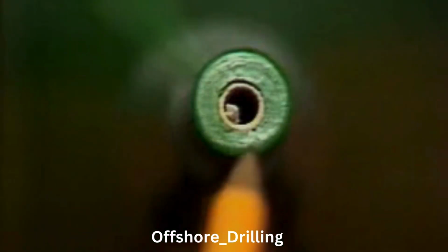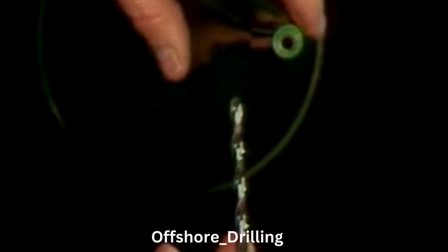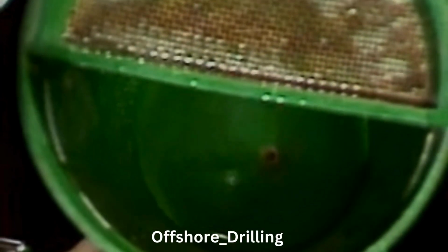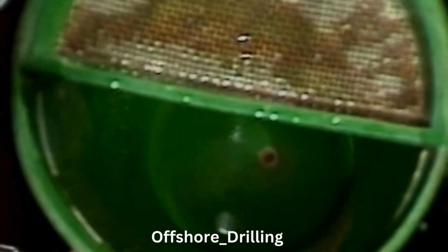If it's too slow, it's probably because the funnel is plugged. A 3/16 inch drill bit will correct that. If it's too fast, the hole's too big, you'll need to get a new funnel. Now let's measure some mud.